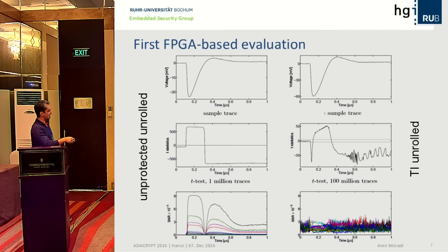You can also compute the SNR, the signal-to-noise ratio, based on the plaintext nibbles, because the Sbox is 4-bit, and because the Sbox is a bijection and the key addition is also linear, you can compute the SNR based on the plaintext nibble, which will directly map to the SNR calculated based on, let's say, the Sbox input or Sbox output.